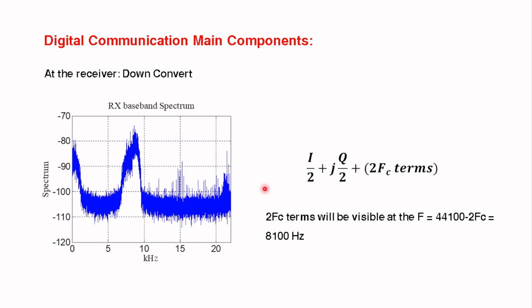So it's important to keep in mind that because we have a fixed sampling frequency, we cannot see any frequency more than half the sampling frequency, which is basically here. At any frequency more than that, we will have an alias of it lower than half the sampling frequency.